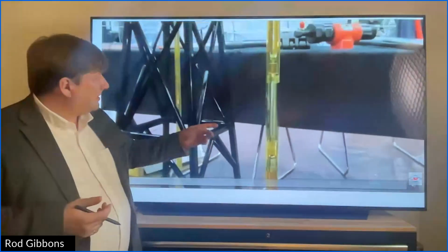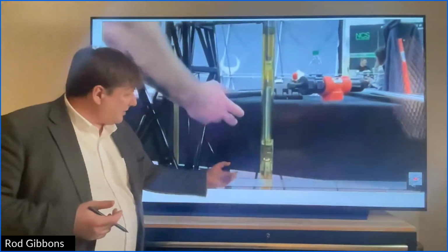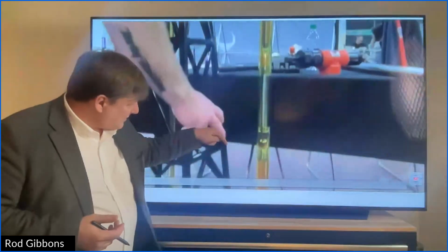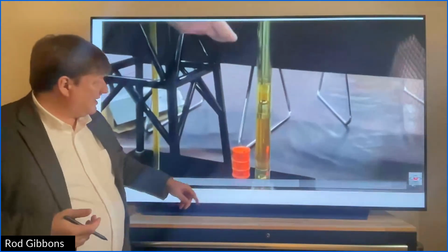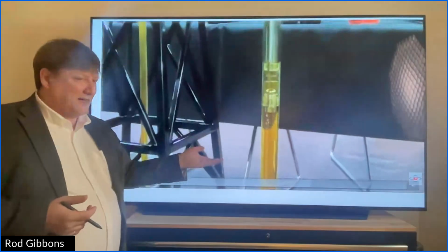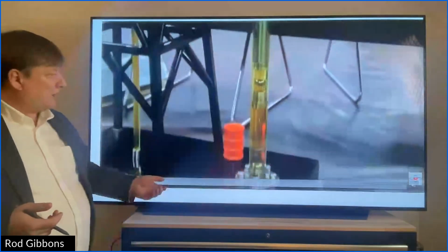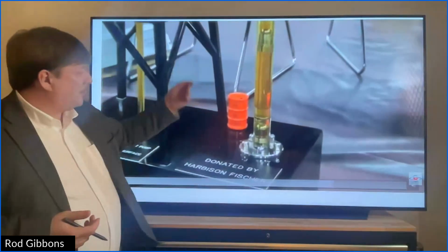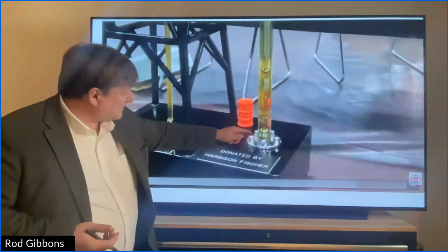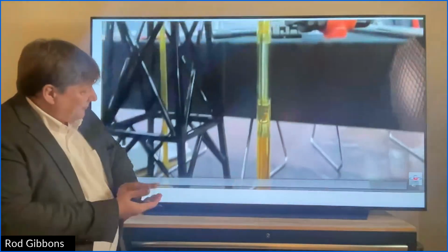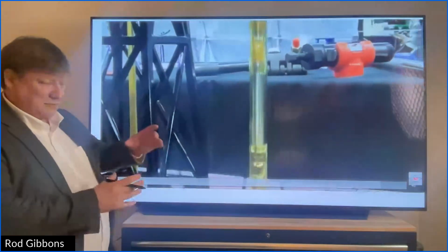You can see, here's the traveling valve. It comes up, it's on its seat. Now as it goes down, see, it floats, and the liquid goes past it. It comes up, it's seated, it's going to lift all that liquid up. It goes down, and then here's the standing valve. As it's coming down, that standing valve seals off on the downstroke to keep that fluid in place.